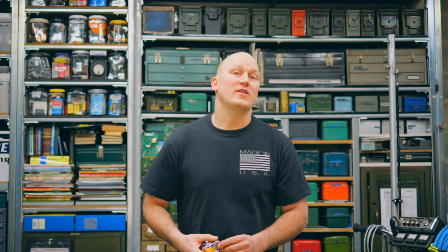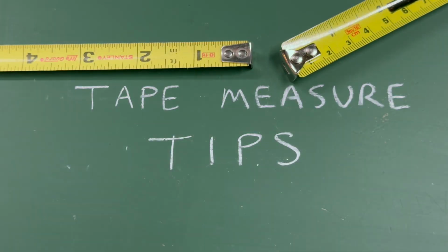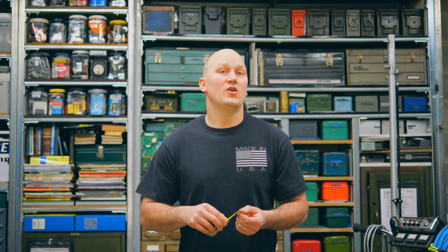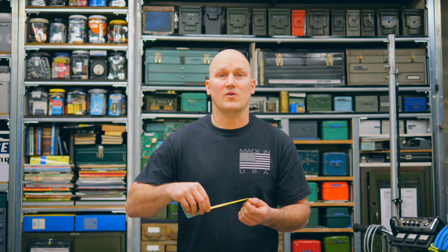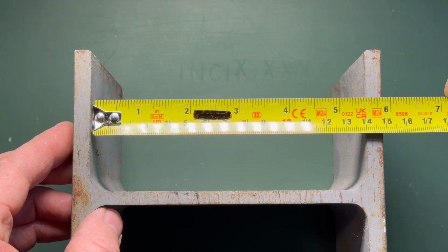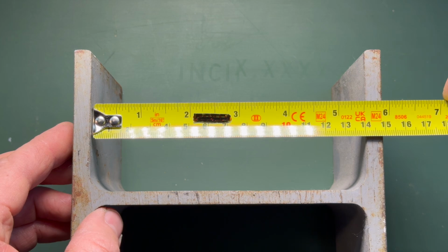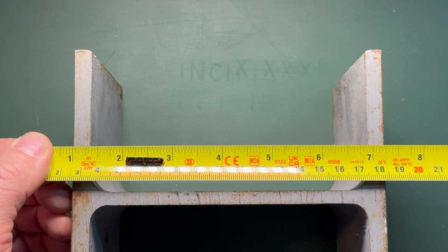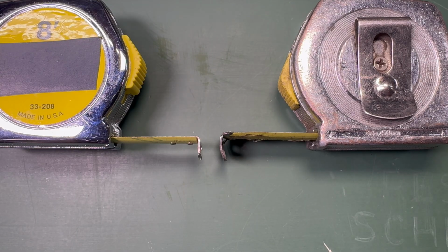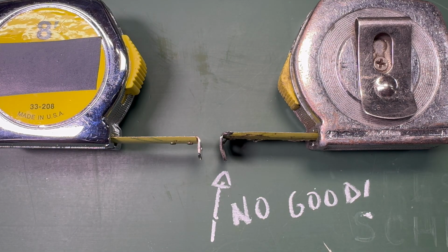Whether or not you are measuring with inches or meters, here's some tape measure tips. The hook end of a good tape measure has a little bit of slop or play to account for the thickness of the hook when making outside or inside measurements. Make sure you allow the hook to pull or push into the tape as appropriate. To avoid the play in the hook end for a bit more precision, you can burn an inch, or in reality any amount of the tape. Just remember to account for what you overhang and subtract it from the numerical reading on the tape. If you drop your tape measure, check the hook because it can bend and make your measurements come out wrong.